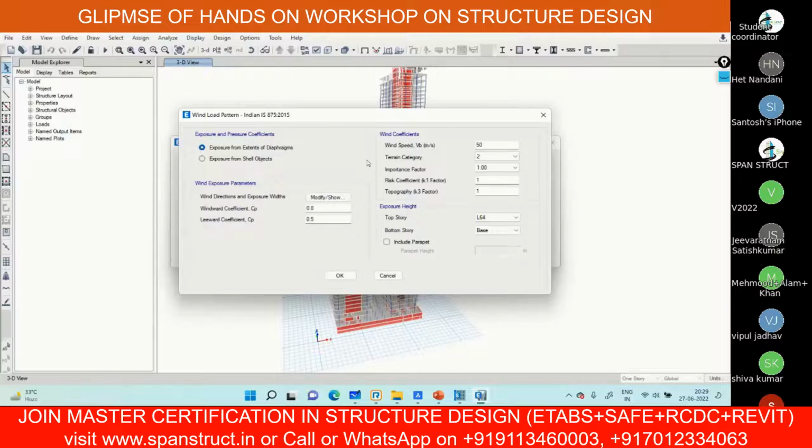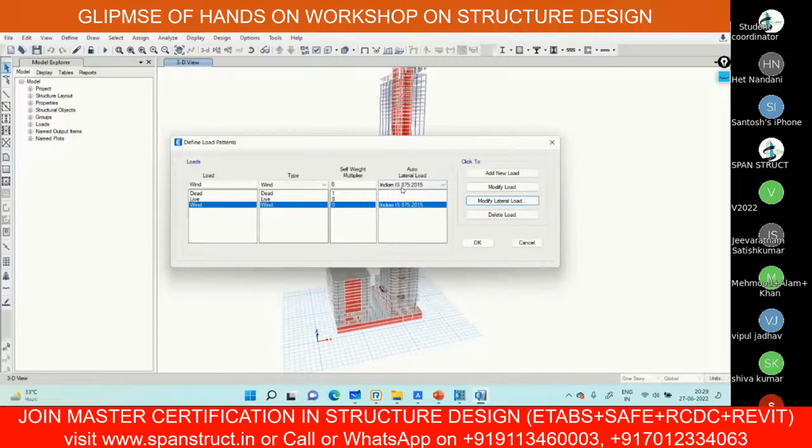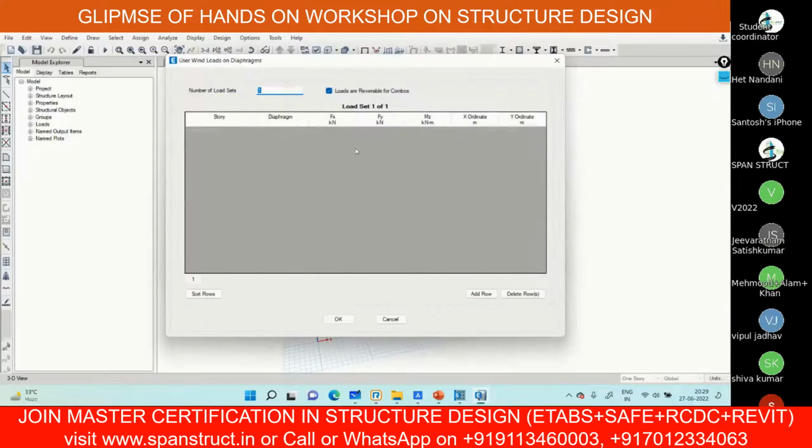But when it comes to the gust factor, in that case, auto lateral load will not work. Then you have to select the user load here and you can modify this lateral load. Can you see here that all the things will come here. When you apply the diaphragm, then automatically story will come, diaphragm will come, forces will come, and Fx, Fy, Mz values will come, and you have to apply manually here. Now you got it. Whenever you have to apply the gust factor, you have to apply through the user load. And when you have to apply through the codal provisions, like simply if you have to apply the wind load, you can take the help of the diaphragm extent and shell object, which is automated.